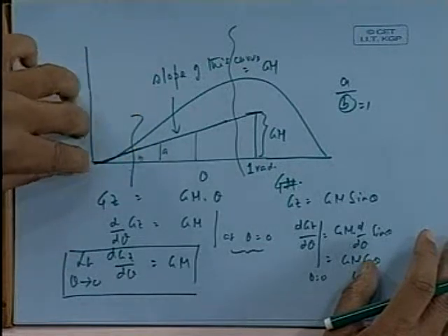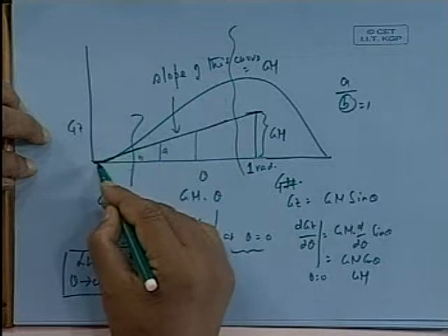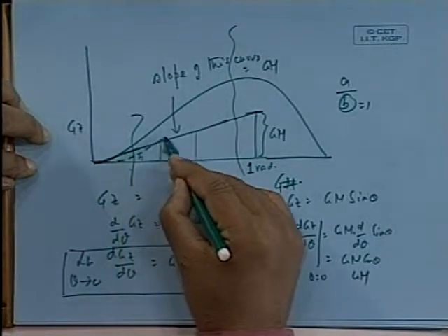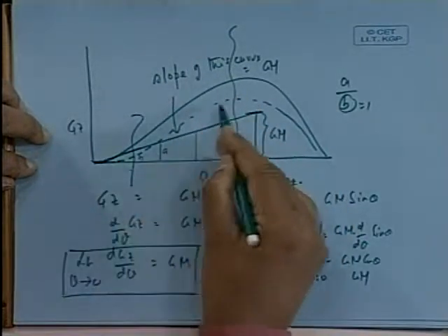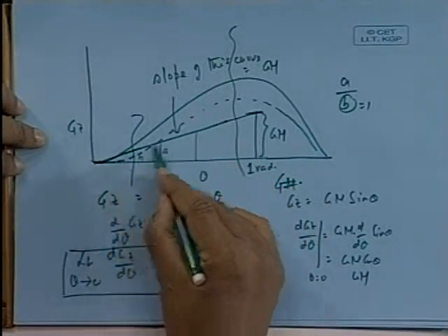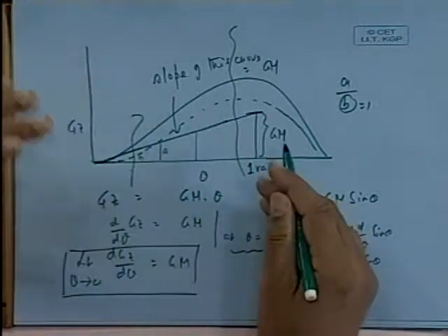This slope therefore tells me, you can see from the slope, the curve can actually have a 0 slope and come up like that. See the nature of the curve this way, this S-type curve, I have already discussed that a little bit earlier, tells me that even if GM is 0, the ship is not unstable. It can be stable later on.